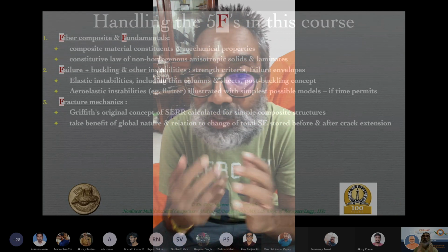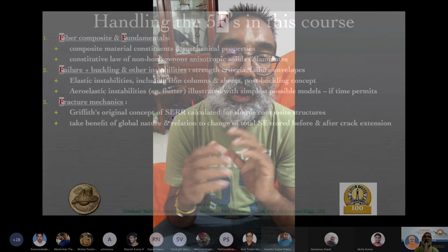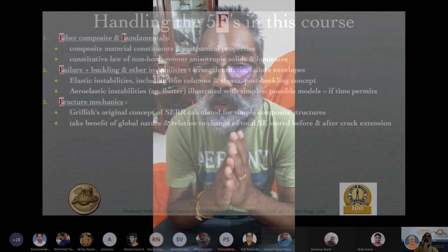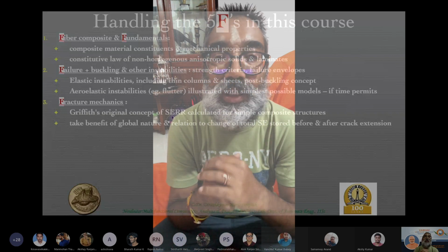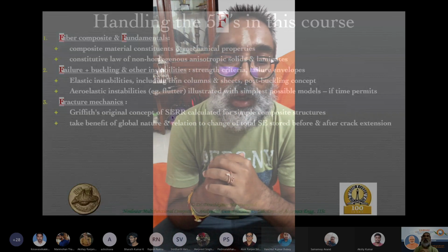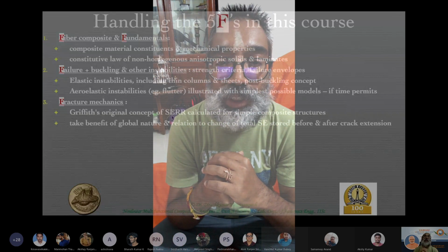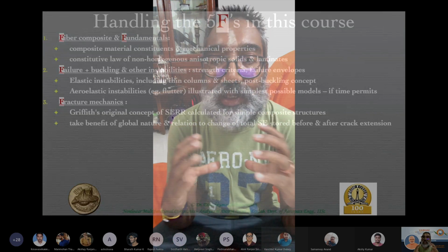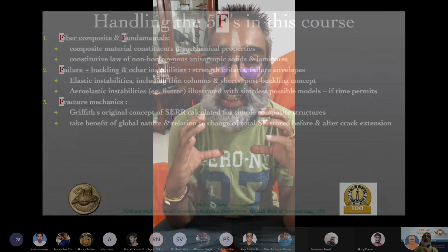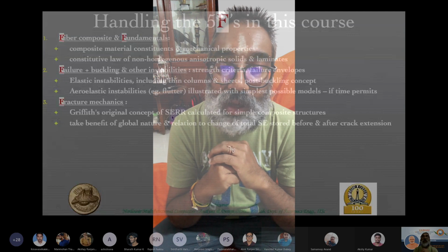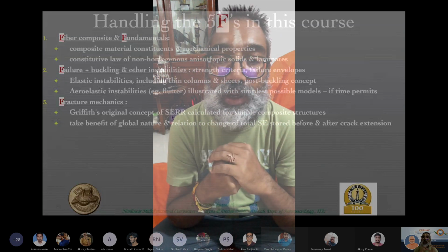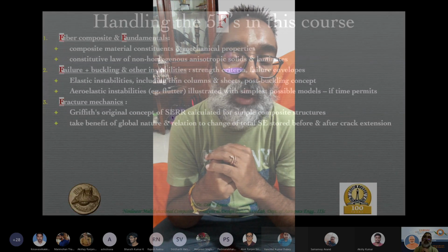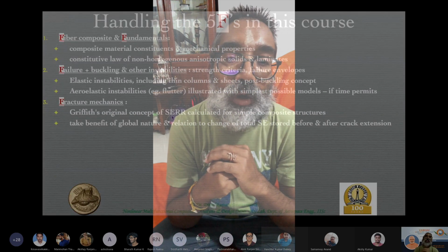That can be very easily related to some of the other fundamental concepts that we'll be dealing with when we are relating stress to strain through the stress-strain constitutive matrix, an extended form of Hooke's law to apply for composites as well, in terms of a matrix now instead of just a single quantity E. That matrix can then be used to formulate the strain energy for a linear material in terms of a quadratic form of the strains.